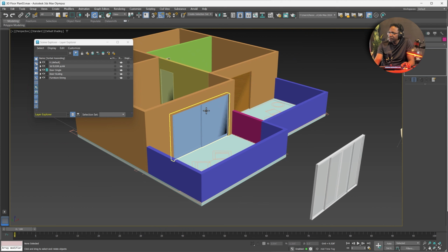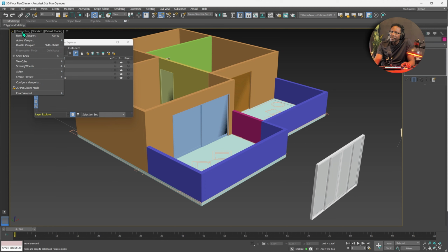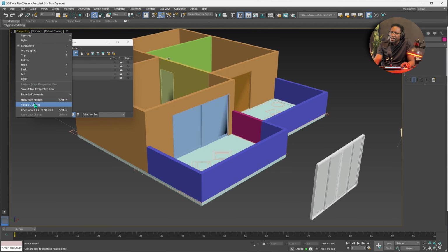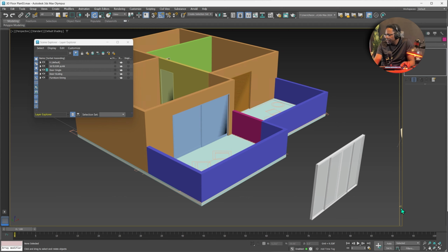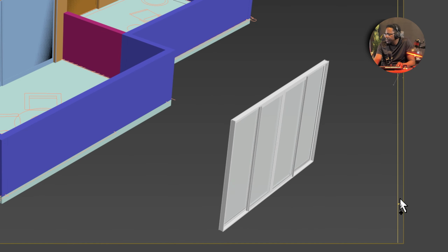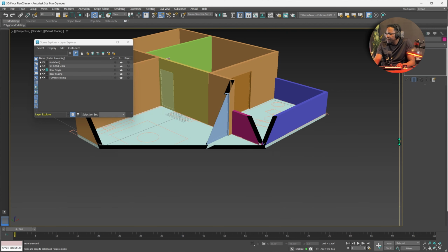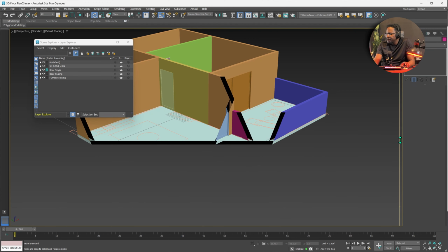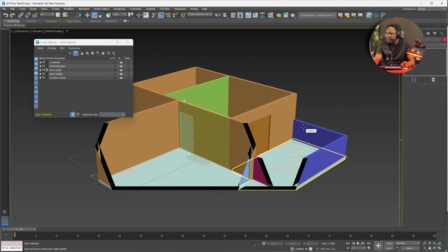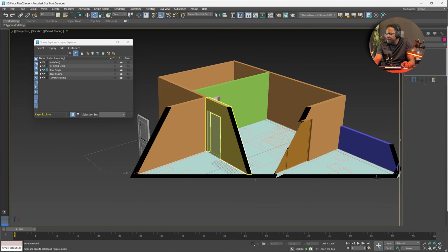So the way you can visually fix that quickly is by going to your viewport settings up here and then going to viewport clipping. And if you notice, you will get this bar that's right here, and this is your viewport clipping. So if you adjust this as you go up, it will clip your view. So now if I move, notice it's kind of clipping into the model.